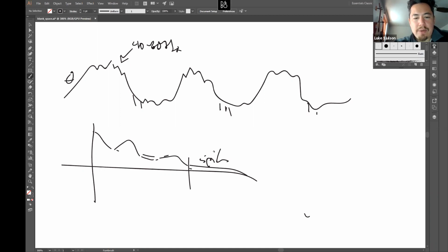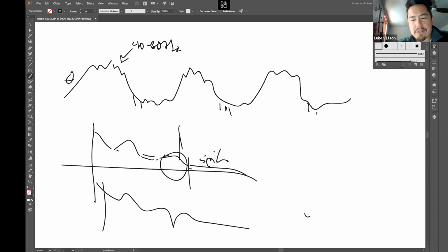What I'm saying is that if you have 60 hertz noise, then all of a sudden, boom, you have that thing right there. And then if you notch filter that, you're going to get something that looks like this. And so you've actually thrown out your signal, the actual physiological gamma oscillation, which is in the same frequency range as the 60 hertz noise. You've gotten rid of that. So that's why this sort of filtering can be bad.